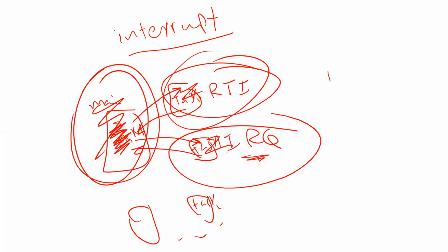Students usually ask me, okay, this is my code, so tell me which instruction here is going to be used to call the interrupt. No, we don't write it. Although an interrupt looks like a subroutine, there is a big difference. In a subroutine, you have to write an instruction to call the subroutine, but interrupts are called automatically when an event happens.